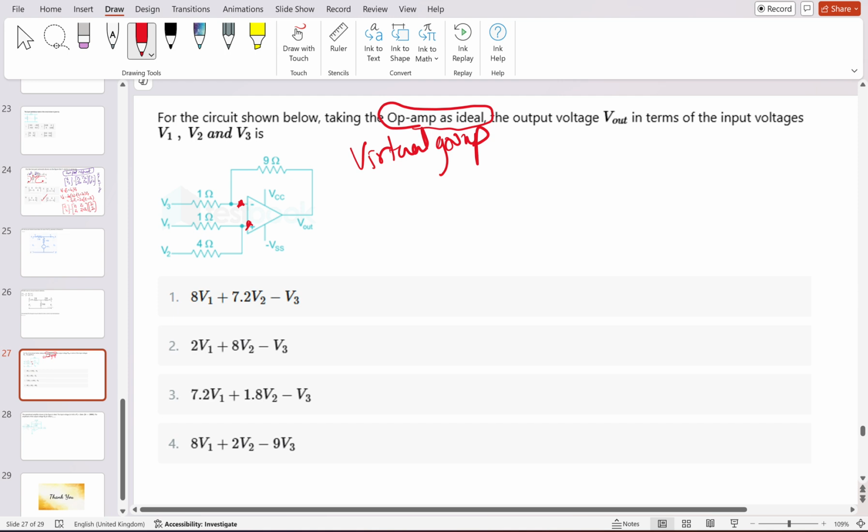Okay. So when you say that here it is zero, here it is zero, whatever voltage comes here will simply be reflected to the other, negative terminal, the node which is connected towards the negative. Suppose I am considering this is V. The same voltage will appear across this node. Suppose this is A, this is B. So the voltage at A will be equal to the voltage at B, which will be equal to V.